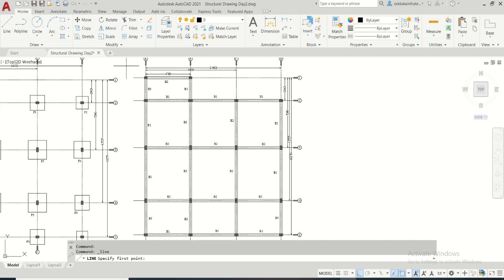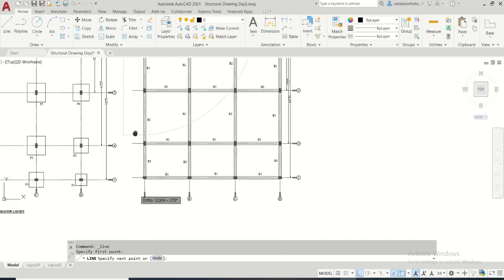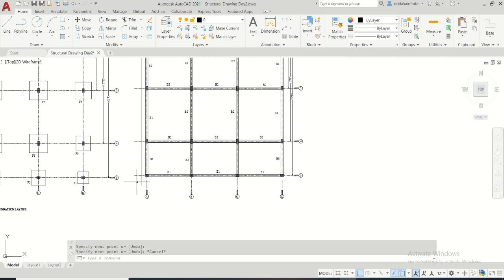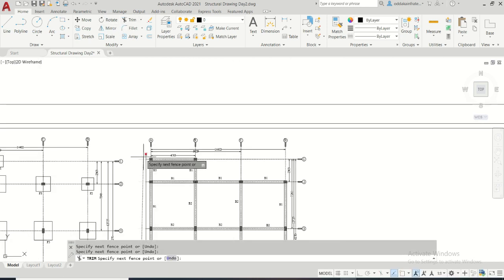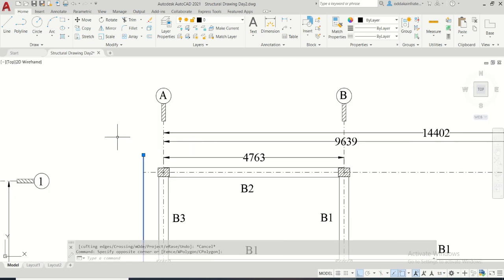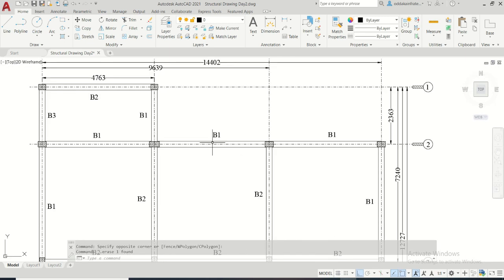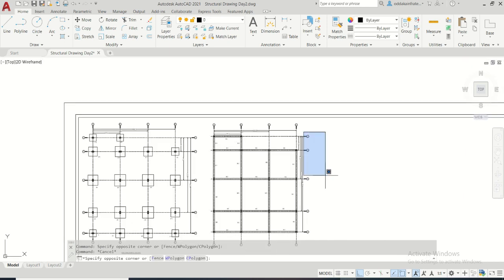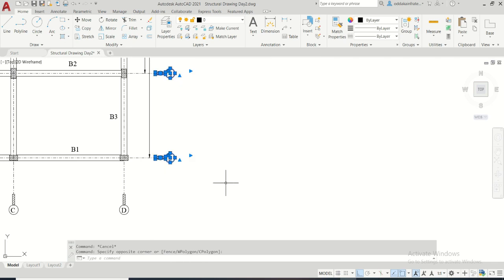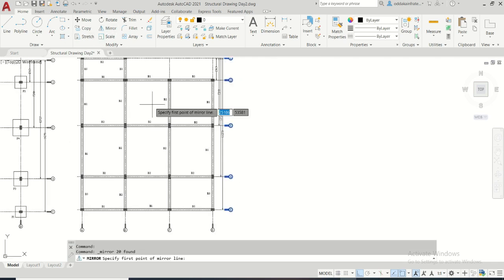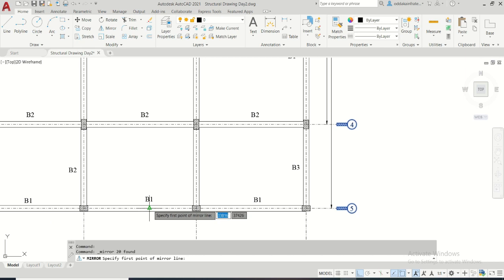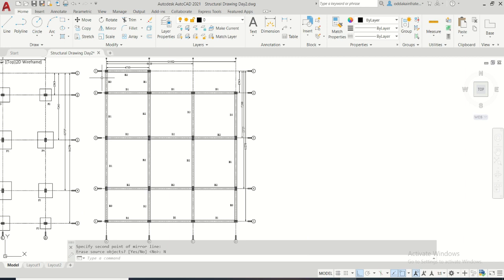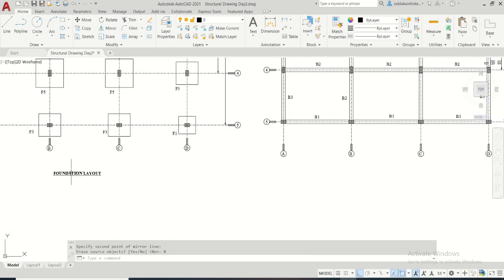And if you want it closer, you'll just need to select the line here and use this trim command to simply trim the excess portion. Select this, delete, and then select this line, the middle is coming around here. So select this from left to right and then use the mirror. Search for the middle option. So this is the middle option, top, ortho, erase, no. So we'll have this layout.